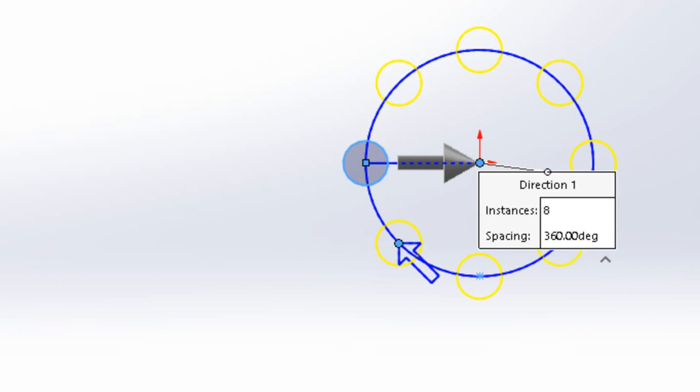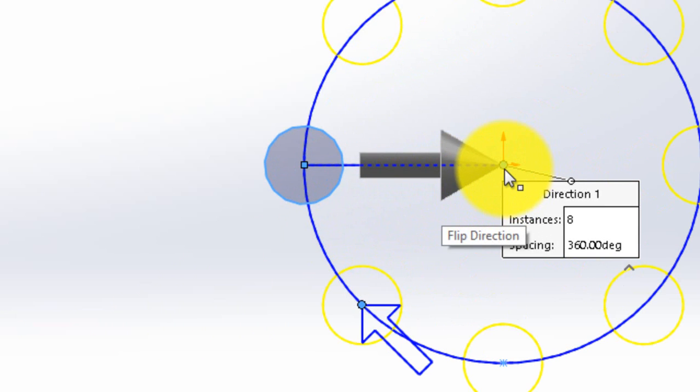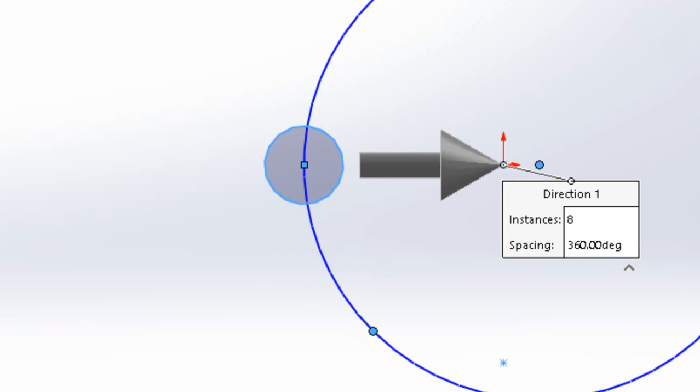I can also change my center point coordinates by giving a value over here, or if you have a specific radius, you can give this radius. If you give a radius, or if you change the angle, the position of that point will change. Let's say I want here not 6.33, I want 7.5 centimeters.